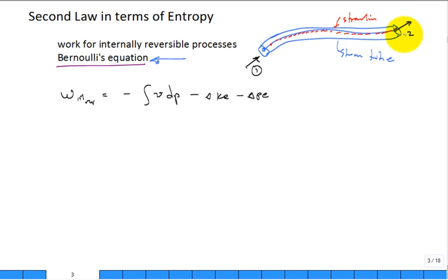Hey, that looks like a control volume. Sure is. Is there any other boundary at which mass is flowing in or out of that stream tube? No, just on the inlet and only on the outlet. And then if you apply the first law, with the assumption it's internally reversible, bringing in the entropy concepts and reversibility, you get this equation.